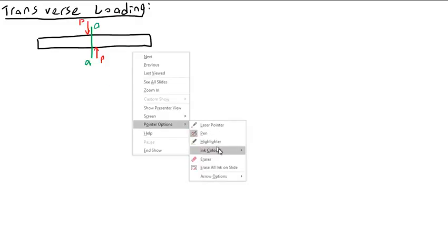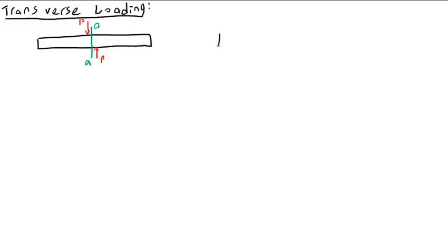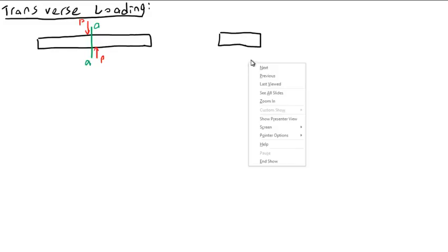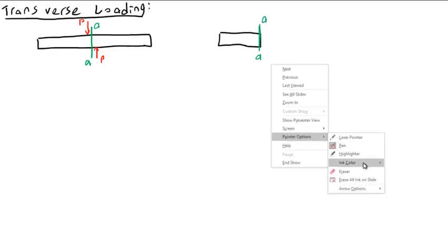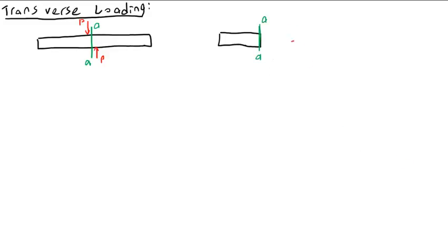So if I draw the cut, I will find, on the left side anyway, that there are the following forces. So this is cut AA. I have force P here. And then I have my shear, again, drawn with the correct positive orientation, normal force, and moment.